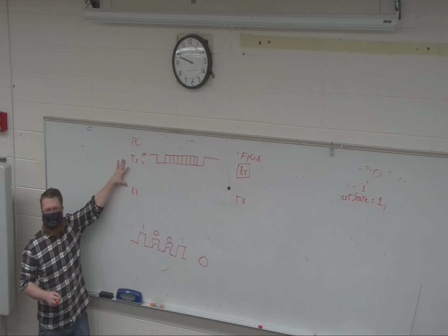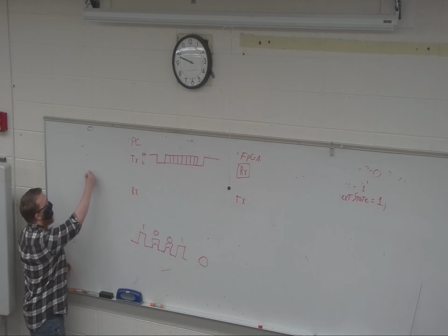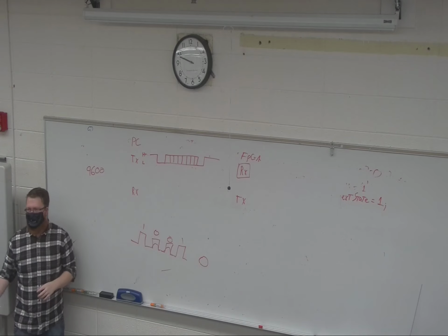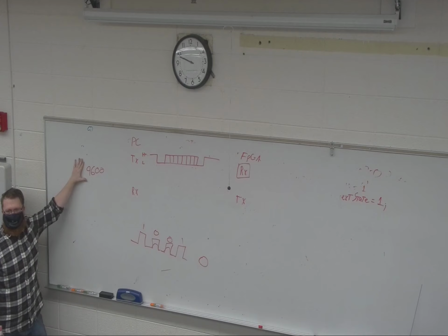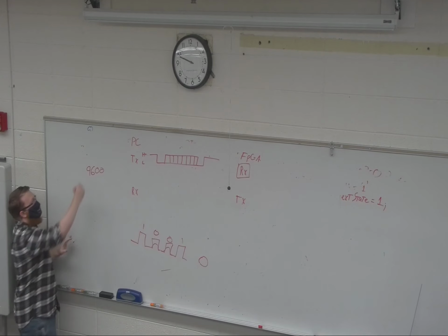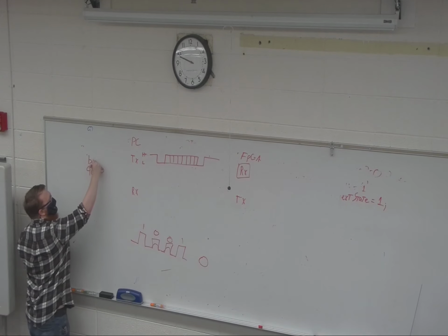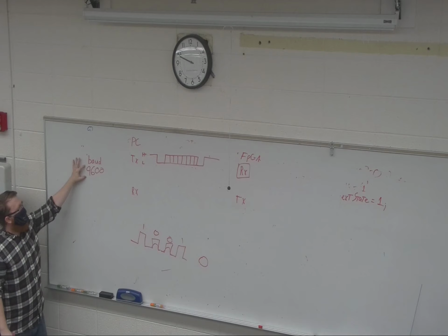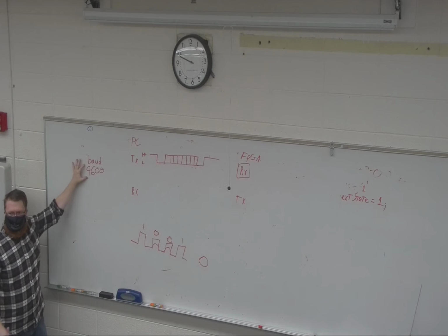UART, like this, is fairly limited. You have some pretty common bit rates. If you look at Arduino examples, they almost always start with 9600. We call this baud, the baud rate, but it's really just bit rate. And so 9600 is really common, but it's very slow.